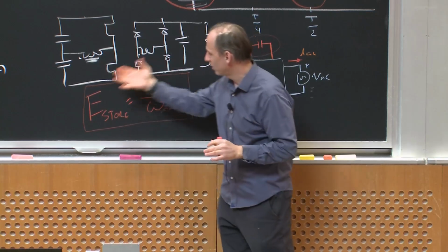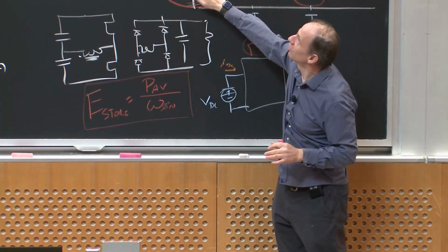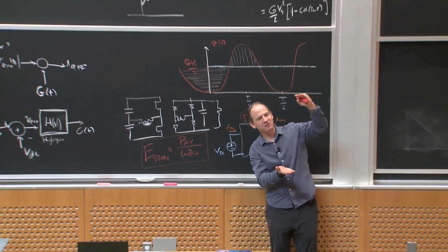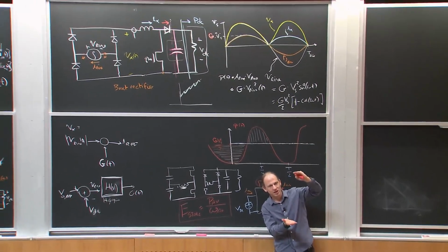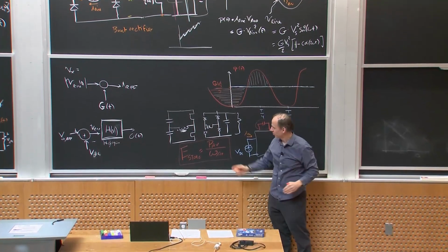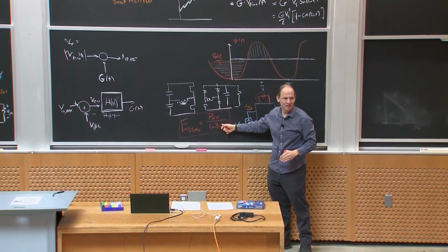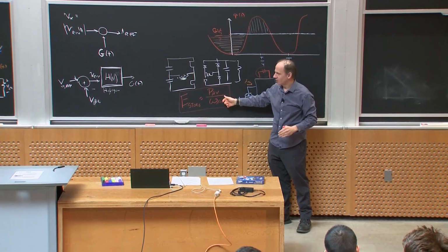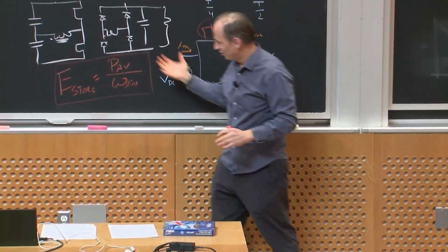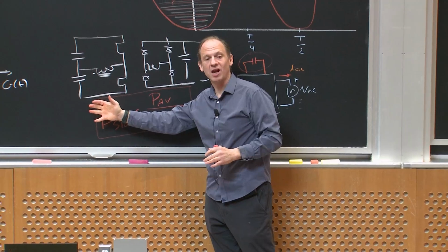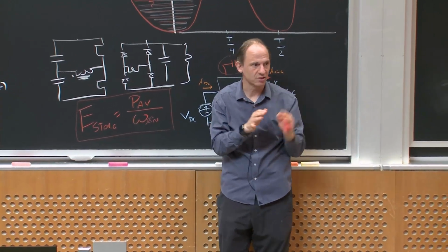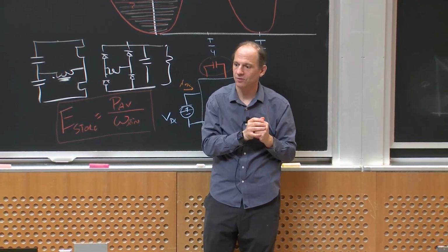And by the way, this is the amount of energy, this is the swing in energy. So if I'm going to store that with a very small ripple on that capacitor, that's 1/2 C Vmax squared minus 1/2 C Vmin squared. If my ripple on my capacitor voltage becomes smaller, the energy storage rating of that capacitor is even bigger than this number by a lot, okay? So there are games you can play, but this is a minimum energy storage you're going to need, and generally if you want small ripple on the capacitor, you need much more than that, and the lecture notes and the text go into the details of those calculations.